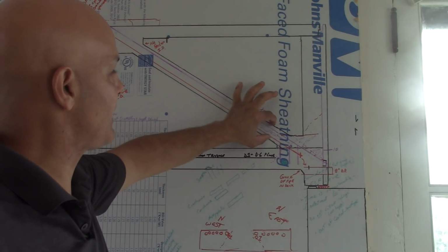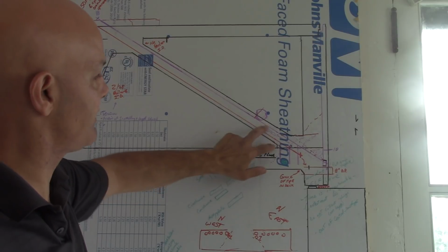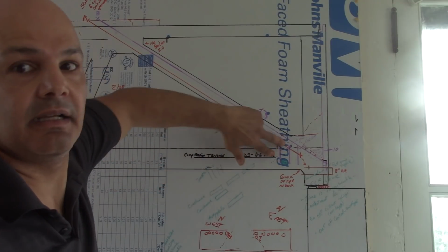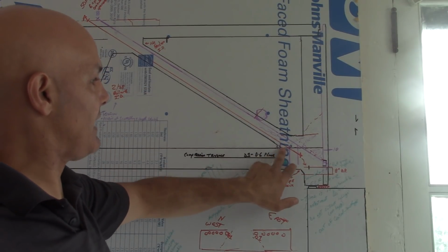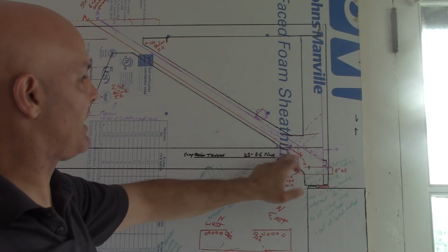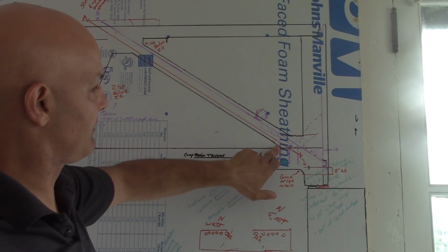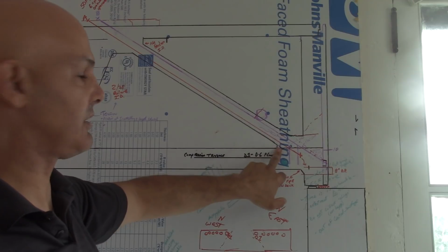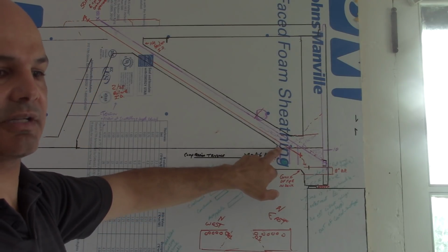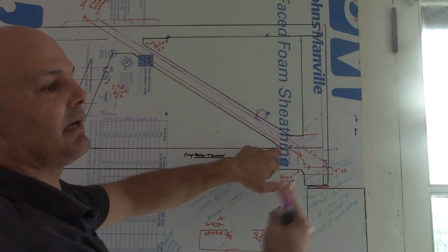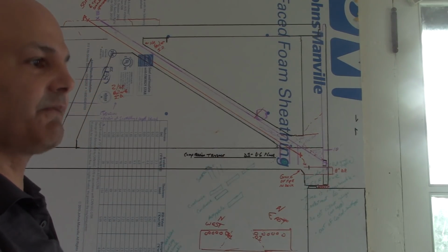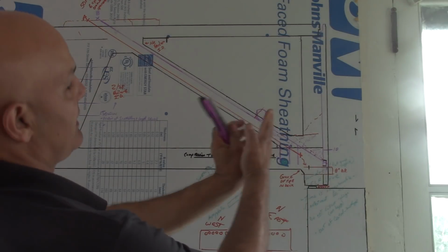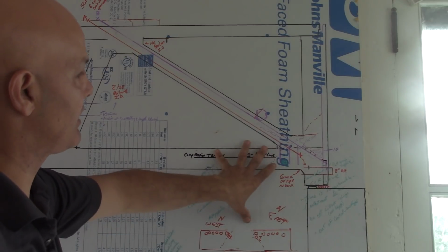Can you add post-tensioning on here? And the conflict between the two of these, the chamfer and the deck, would create a shear like this and cause a crack. Yeah, you could do that, but you'd also have to show me movement and compression, and possibly it would be a compressive break here. When I investigated that crack initially, it's a shear crack, but more like a flexural crack. It's upside down. I'll show it to you in the cardboard.